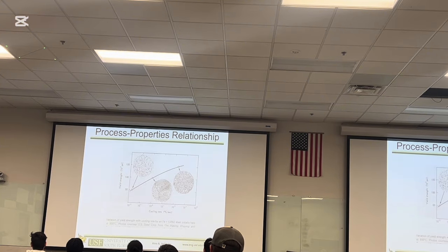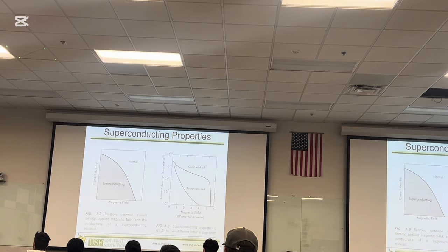So we'll talk about the mechanisms of failure, what we mean by failure, why materials fail and how they fail. Every time you slam the door in your car, you want to be able to open it. If the geometry of that door changes somehow, that door would not latch next time, right? So that's one of the design criteria, is to just have elastic deformation. I already showed you a similar slide, but on the right you see cold worked metal versus recrystallized, and also we're going to discuss what that means.